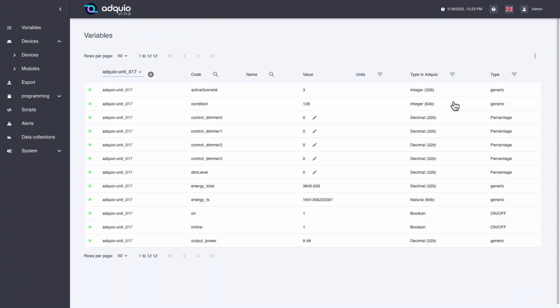So, if we enter its variables, we see that we have here the dimmer of luminaire 0, of luminaire 1, of luminaire 2, and of luminaire 3, and that we have a control with which we can regulate all 4 at the same time. Therefore, if we want to turn on this luminaire, we will simply put a 1 and press enter, and this luminaire will be on. Dim level sets as 0.25 because it is a quarter of the luminaires. If we turn on another, as you can see it puts 0.5. They are values in per-unit, times 1, okay? If I want to put 20% here, I would put 0.2, okay? Very good. And since this is the main one, if we put a 0 here, they all turn off.